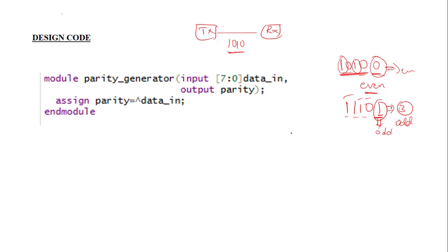How do you get 0 and 1? Now see 1 0 1 0. You know the XOR operation. The truth table is 0 1 1 0, so for the 0 0 combination we get 0, for 0 1 we get 1, for 1 0 we get 1, and for 1 1 we get 0. This is our XOR truth table.